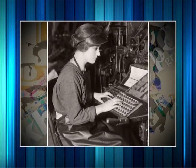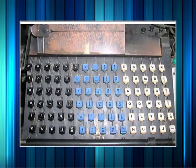Hence, Linotype, a significant improvement over manual typesetting. The Linotype machine operator enters text on a 90-character keyboard. The machine assembles matrices, which are molds for the letter forms in a line. The assembled line is then cast as a single piece called a slug of type in a process known as hot metal typesetting. The matrices are then returned to the type magazine from which they came.